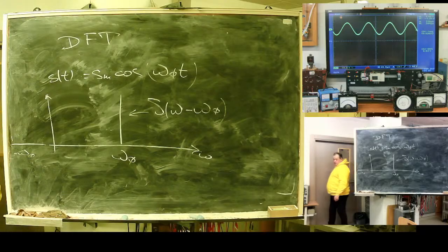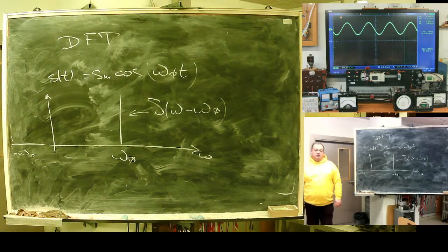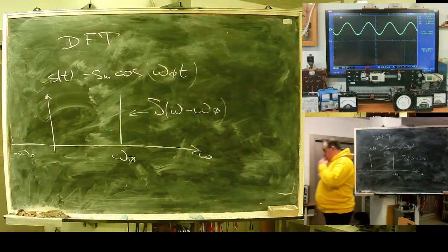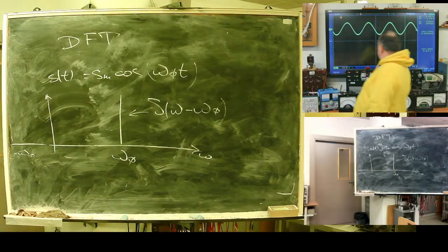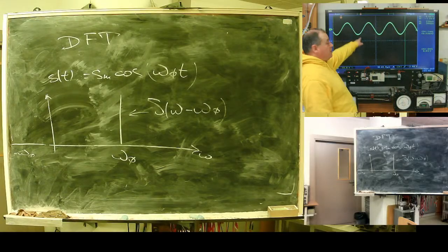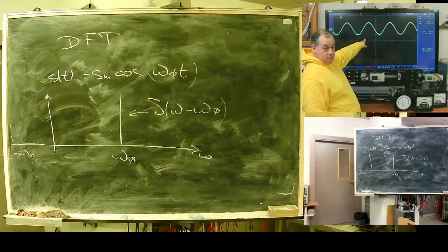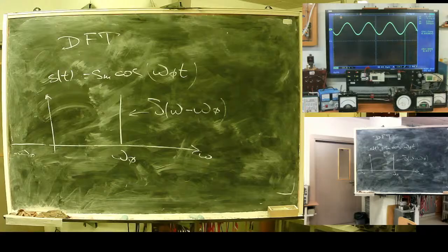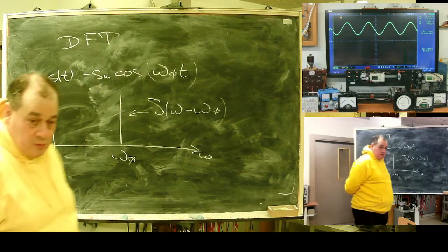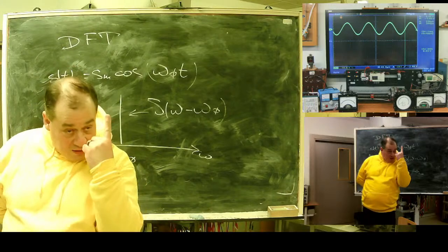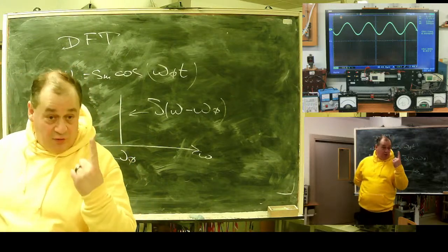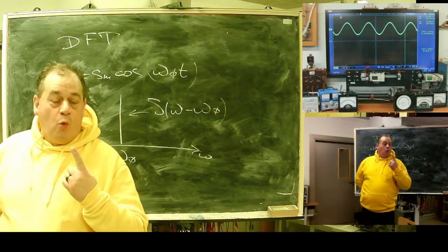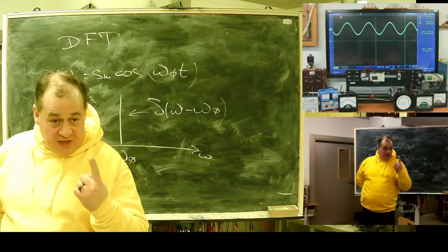But as I wrote, DFT will produce only the positive part. Okay. How many frequencies do I have here? Now, here, the yellow line. How many frequencies? One frequency, 10 kilohertz. So its discrete time Fourier transform should yield one single value at a frequency of 10 kilohertz.